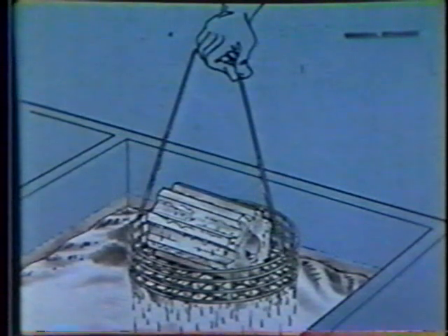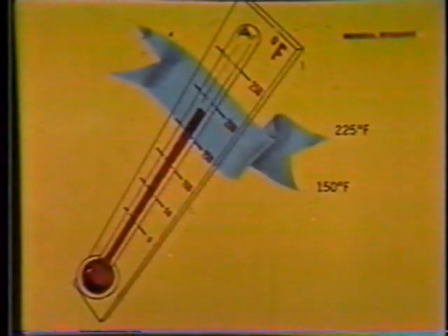Thickness of water-based developers is controlled by bath strength. Specific gravity is measured with a hydrometer and developer or water added as needed. The specimen, on removal from the bath, is positioned so that fillets and recesses can drain. Depending on specimen thickness, the drying temperature used for most applications is between 150 and 225 degrees Fahrenheit. Drying time should be just long enough to dry test surfaces.